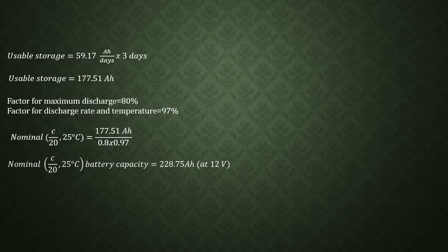We have considered 80%. Also the factor for the charge rate and temperature, 97%. Now the battery capacity for this battery is 228.75 amperes hour at 12 volts.